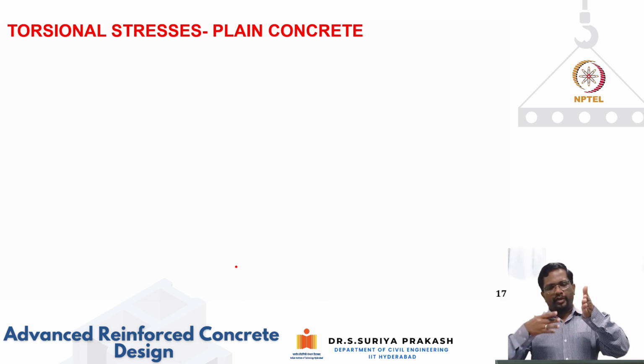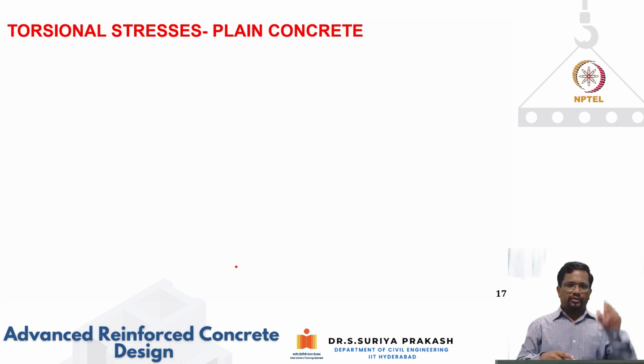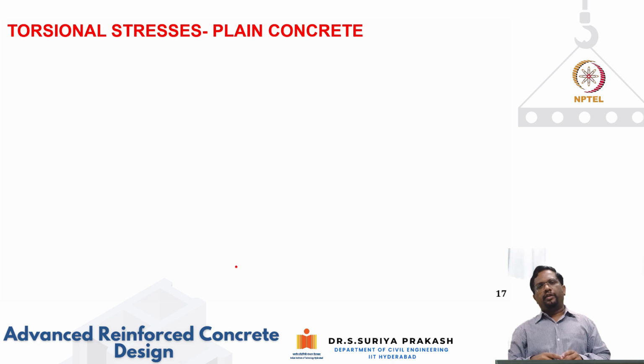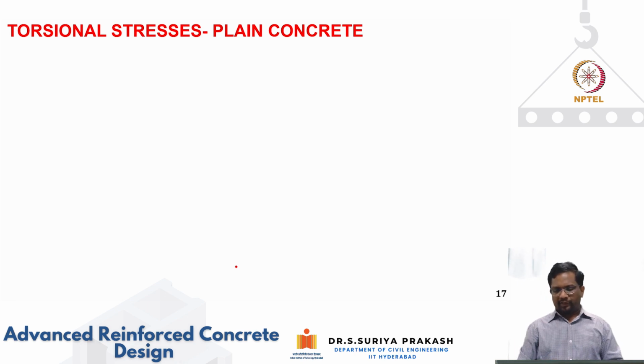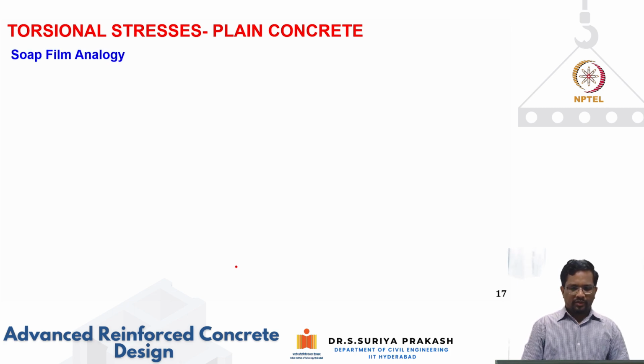When we have a primary girder and a secondary beam, and the primary girder is undergoing rotation, the primary girder torsion stiffness will contribute, and the secondary beam will contribute in flexure. So at the joint, when you are calculating relative stiffnesses, you have to include the torsion stiffness of the primary girder and the flexural stiffness of the secondary beam. Accordingly, you can see how much moment you can transfer to the primary girder.